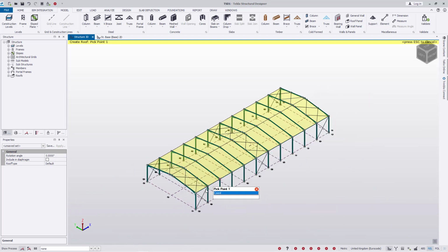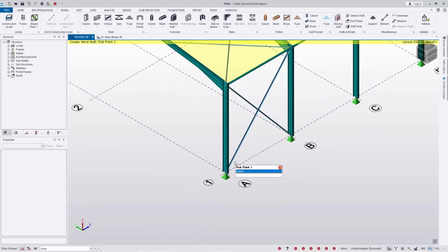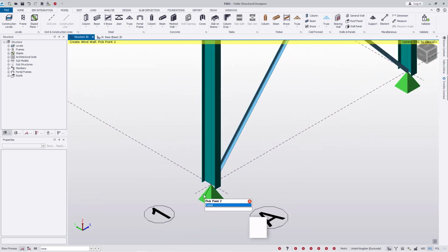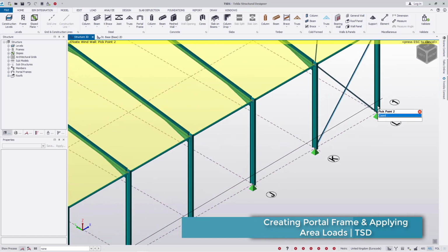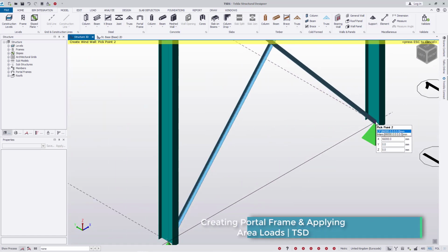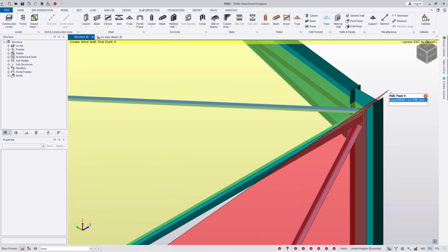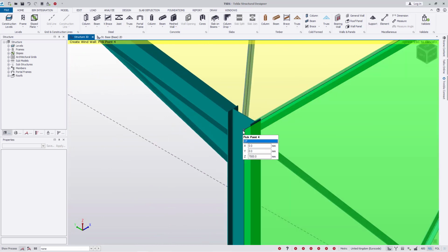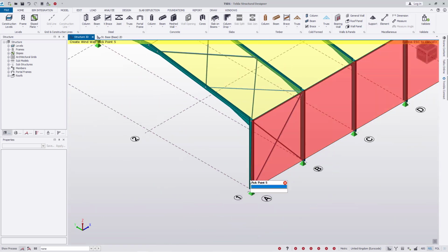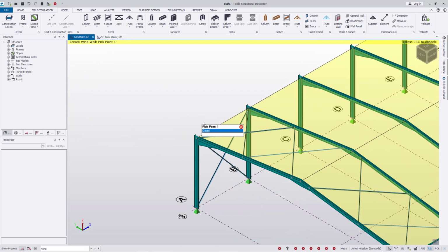So let's now lay the walls. I'll come to walls here. I'll place the wall panel from this spot, and that will be my initial spot. So I'll go all around and come to that spot to close that polygon to create a panel. So let me move to this spot here and move all the way to this far end here and place another point here, and now I'll snap on my initial spot, and that is my first panel.